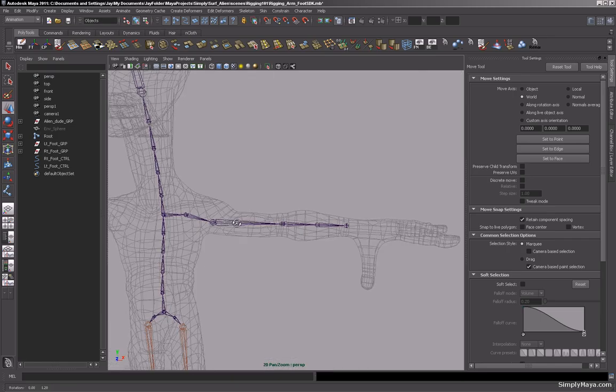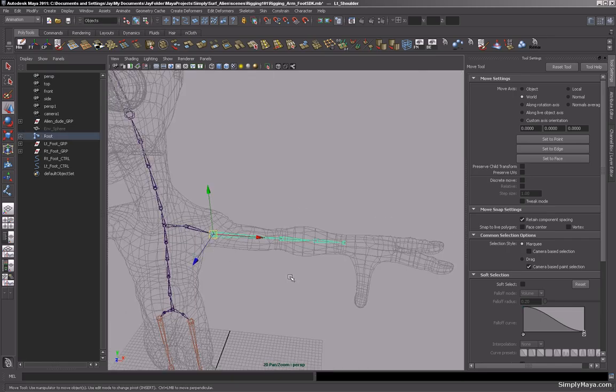We're going to use this for the arm. But what we're going to do, we're going to start the IK here, and we're going to end it on the forearm. And then what we're going to do is we're going to push that along the actual end effector of the IK handle, and then once it's positioned here, we're going to drag it and move it to the end of the wrist.